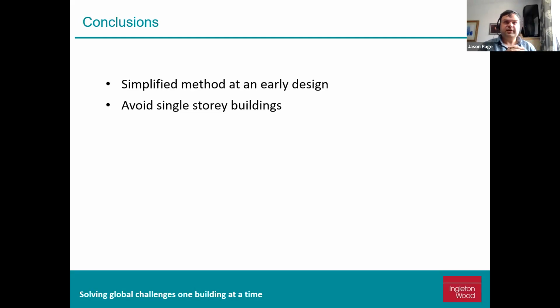There could potentially be an argument that windows on the ground floor in private secure spaces are not open to an opportunistic burglar. This is an interesting argument and not one I've tested through building control myself, but it could be worth a conversation at an early stage. As if you can design your single-story buildings with bedrooms only open to private garden, that could potentially satisfy this element. Otherwise, you will need to consider security bars, secure ventilation options.